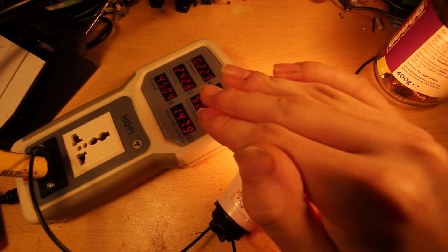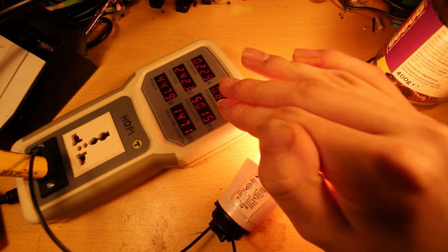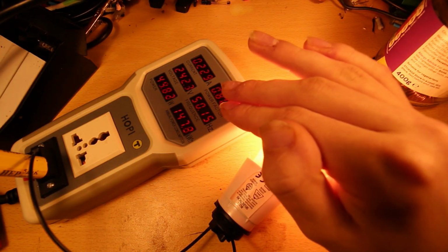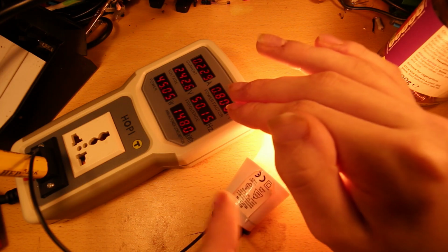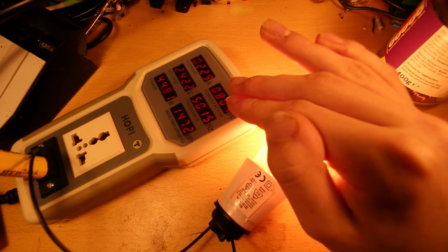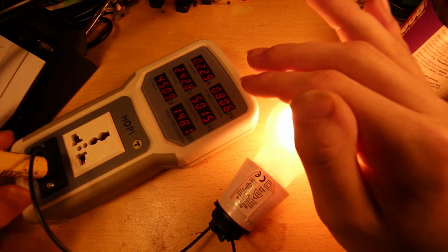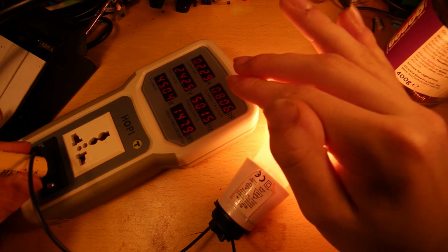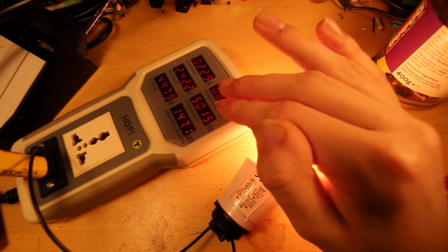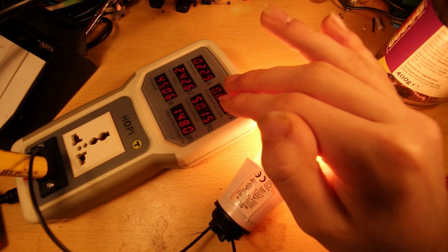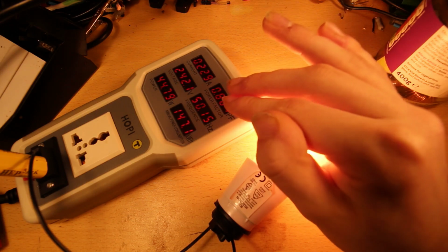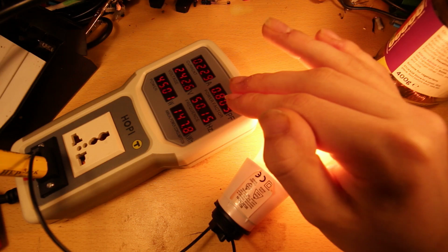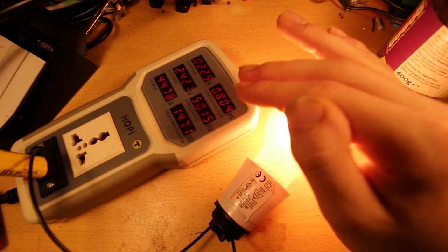I'm not covering that very well, am I? The actual dissipation from it would be less, but still, 83 watts is a lot of power. That's twice as much power as this light bulb is using now. Whereas this capacitor, I can touch it outside, is not even warm. There is no dissipation whatsoever, so you can see in that way it's more efficient. However, the power factor related losses are problematic on the scale of a grid.